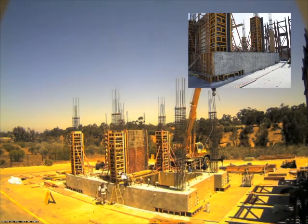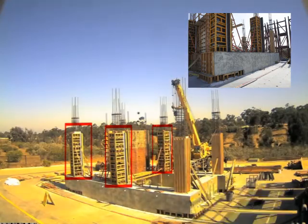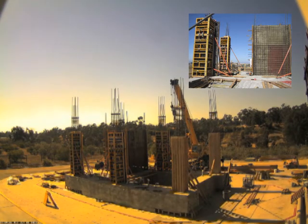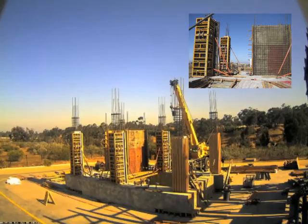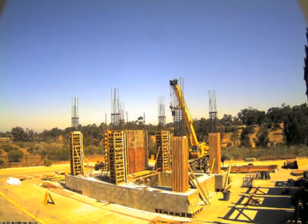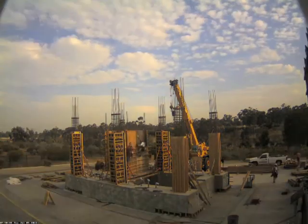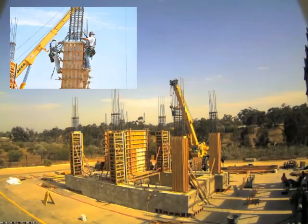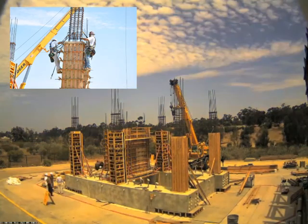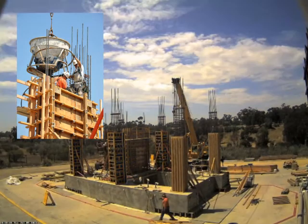Rebar cages were then placed and concrete mix was poured. In conjunction with the placement of the shear walls, the column formwork for the first floor was installed and concrete was poured and allowed to cure. After the concrete had sufficiently hardened, the formwork for shear walls and columns was removed. In order to decrease costs and be environmentally friendly and efficient, many portions of the formwork were reused in the construction of the other portions of the building. Therefore, special care was taken to avoid damage to the forms while concrete was being poured.